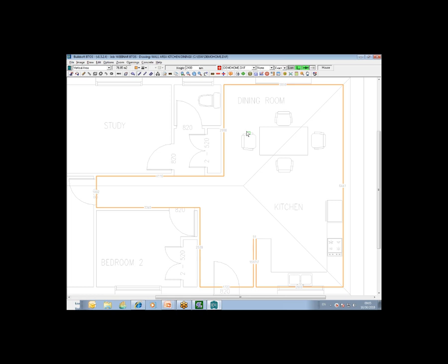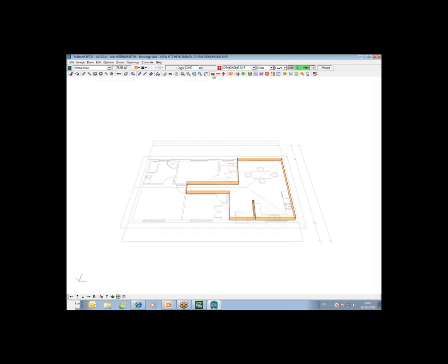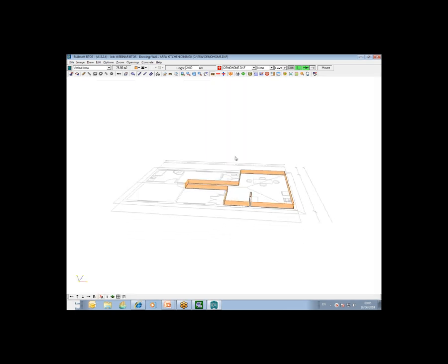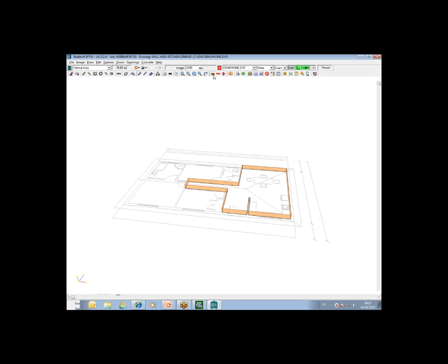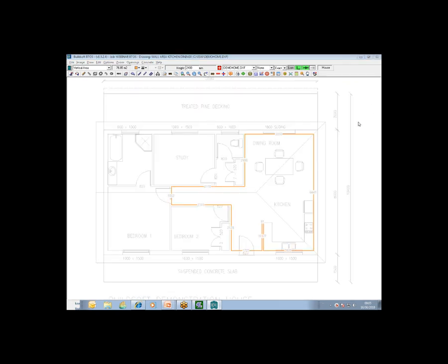When you're dealing with vertical areas or volumes, or volume by length, which we use generally for strip footings, you can use this 3D option, which allows you to view your takeoff in a 3D type sense. That is on the toolbar, and you can see, it's just an icon with a 3D option on it.